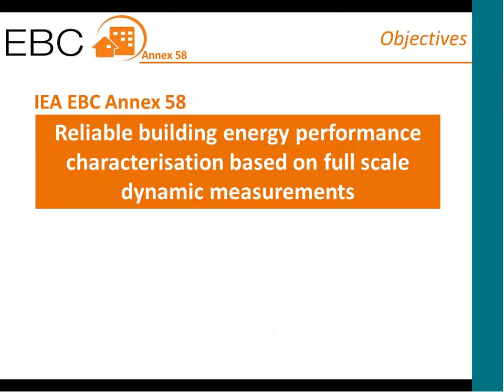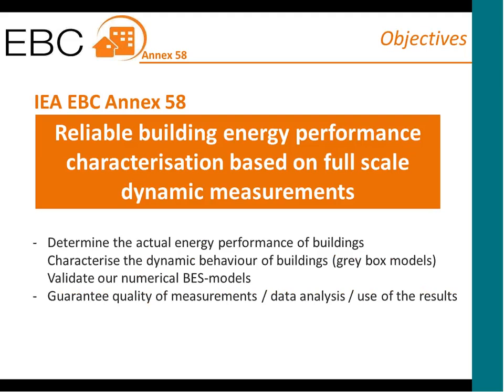So that's the global aim and objective of the Annex 58 research project of the International Energy Agency. We try to characterize the building energy performance based on on-site full-scale dynamic measurements. Some of the objectives in more detail are to determine the actual energy performance, but also to characterize the dynamic behavior of buildings with what we call gray box models. Based on the measured data, we try to simulate the behavior of the building with rather simplified models, but perhaps even more reliable than some of our very advanced models. At the same time, within Annex 58 we did a very detailed full-scale experiment on a building, and we use this data to validate our numerical building energy simulation models.